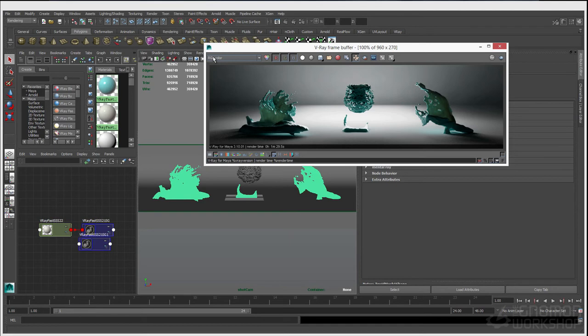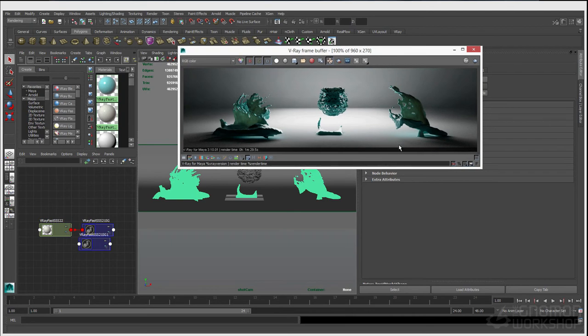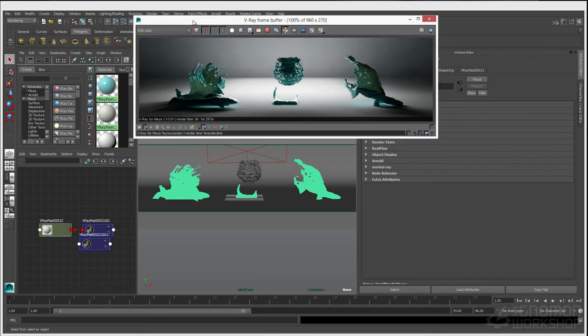Another one of the main ideas of the Vray proxy is that they only will ever be called one time. So when you hit the render button and these 3 meshes pop in, you can have basically unlimited copies of that VR mesh file in your Maya file. Well, not unlimited, but wherever Maya would kind of cap out. But you can basically create unlimited counts of geometry. And that's what we're going to be showing an example of in this first demo. But first, let's talk about how to export our Vray proxy.